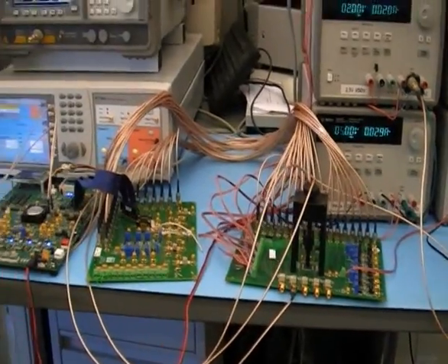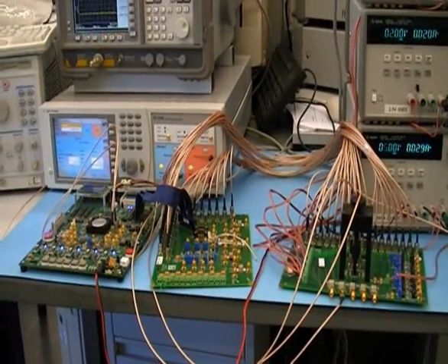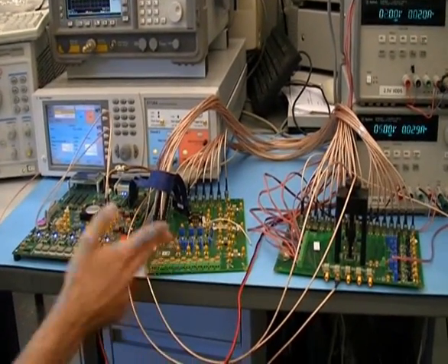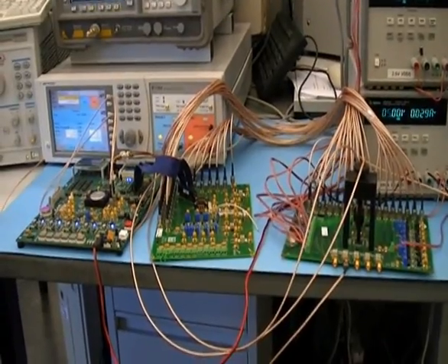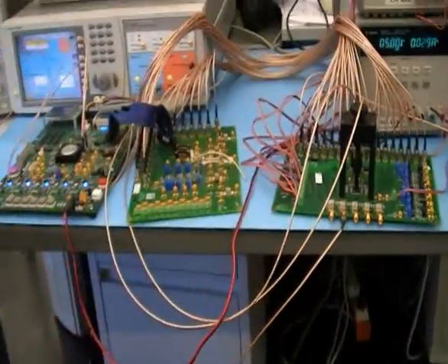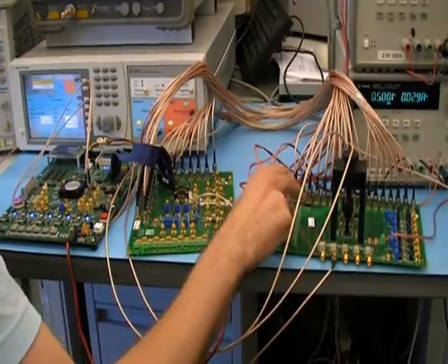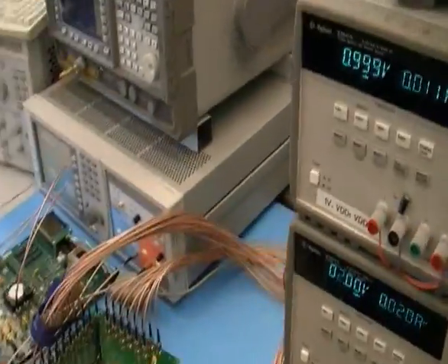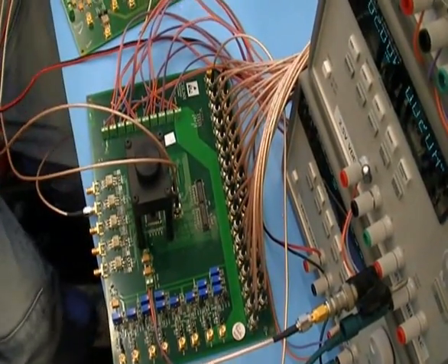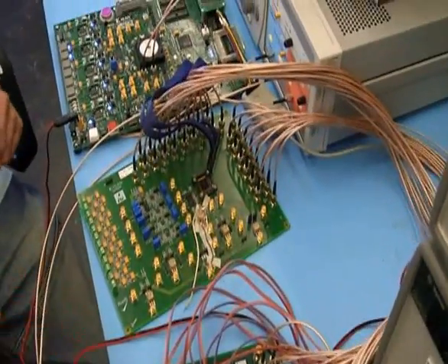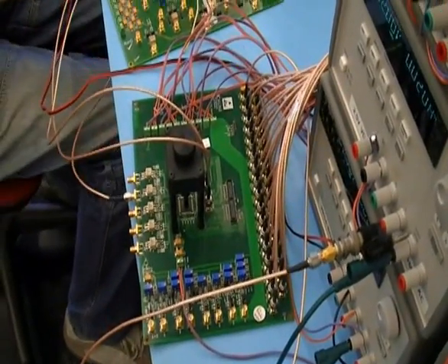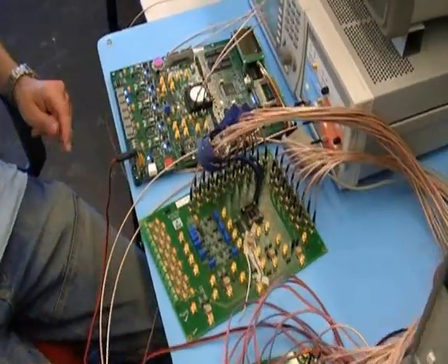Can we go faster? No, if we go faster we get digital faults because of all this wiring. But why all this wiring? Why can't we just simply get this blue cable and connect it here on the test board? There is a design fault in this connector of the test print, and through this fault it's only possible to put 12 signals into the DAC, so 12 LSB digital data. In this manner it's possible to get 16